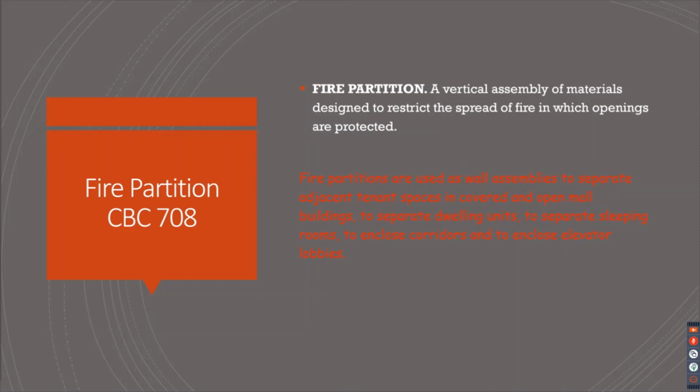In corridors. Those are where we usually see those. I listed the different areas where you see fire barriers. Fire partitions are your corridors, your 1-hour corridors. And they're in other,